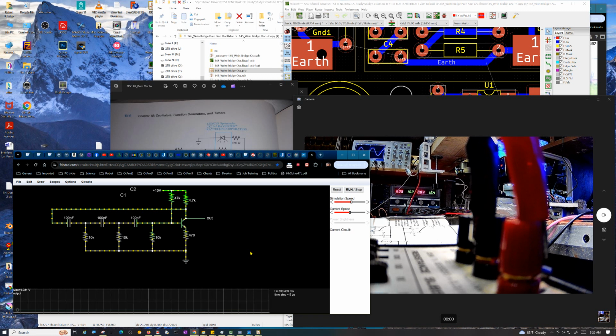If you ever come across any mercury wetted relays on eBay or something like that, well, that's one use for them. You can make a step response. They're basically reed relays, but they have mercury in them, not a lot, but enough that there's no contact bounce. The ESP guy actually did some tests on them. He's got a whole article written about relays, a couple really. He mentioned that in there, and I thought that was fascinating because otherwise I wasn't really sure what to use those for. That was a good idea.